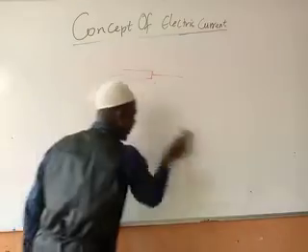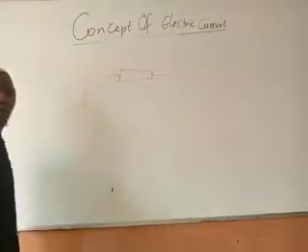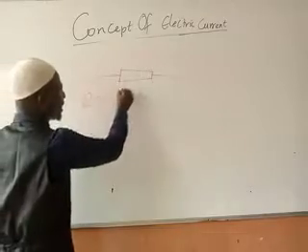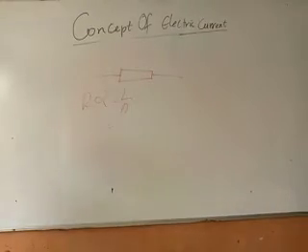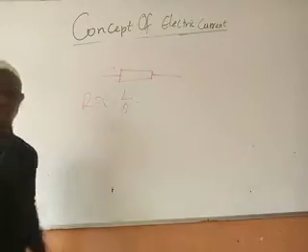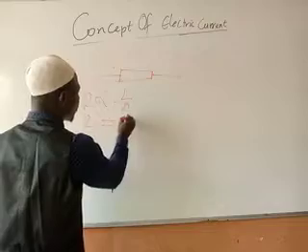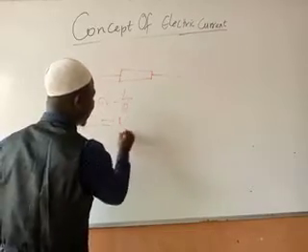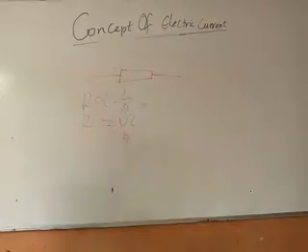So let's use the factors to form an equation that we normally use in calculation. Therefore, resistance of a conductor R varies directly with length and inversely with cross-sectional area. And don't forget, when you remove the variation sign, we are going to put equal to and a constant. Therefore, resistance is equal to constant times L over A, where this constant is called resistivity.